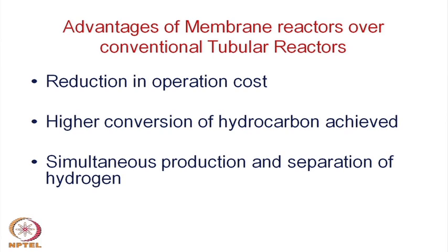But if you can make a ceramic membrane, either a dense membrane or a porous membrane, though we are talking here about dense membranes, those dense membranes can form the reaction chamber itself, because this reaction takes place at higher temperature. The ceramics can be used as the reaction chamber, and if it is a semi-permeable membrane, that property in the same ceramics can also be used as a separation chamber.